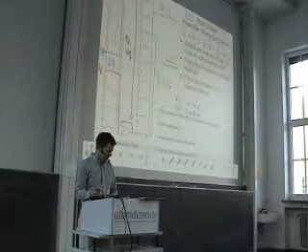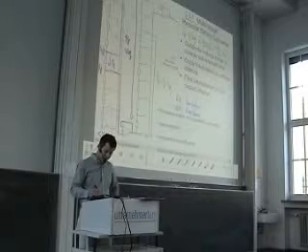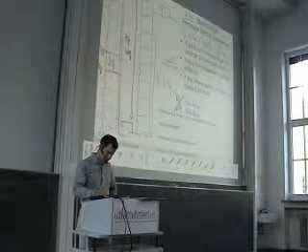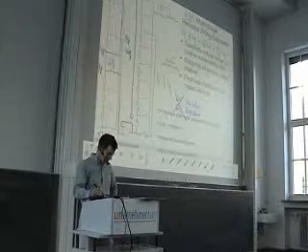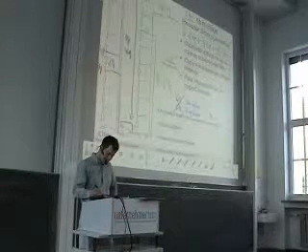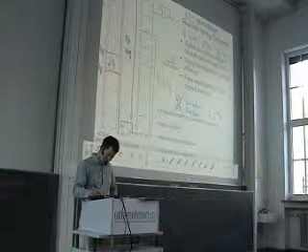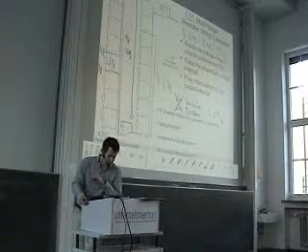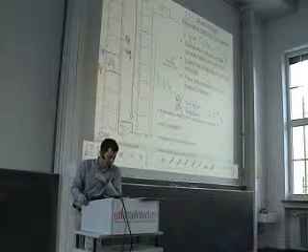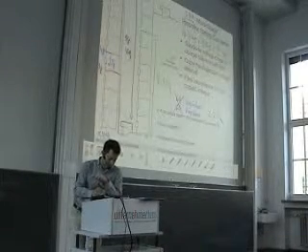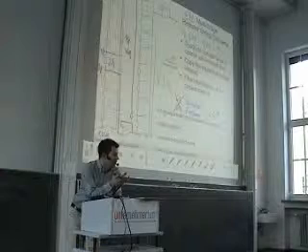converter here. However, we have not 64 switches and not 64 resistors, but now we have 2 times 8 resistors and switches, so we have now 2 times 2 to the power of n over 2. So here we have considerably reduced the number of switches and resistors. However, the price was that we now have 2 additional buffers. This one that copies the first voltage, this one that copies the second voltage.